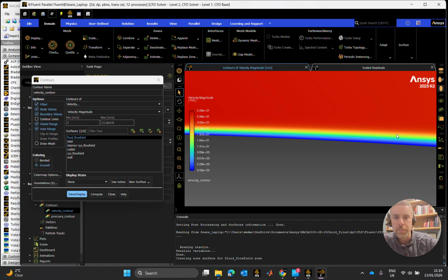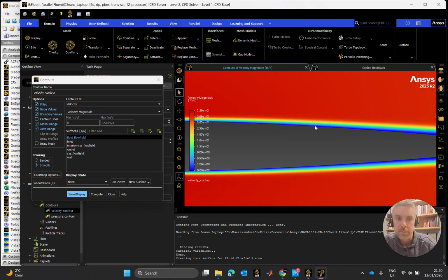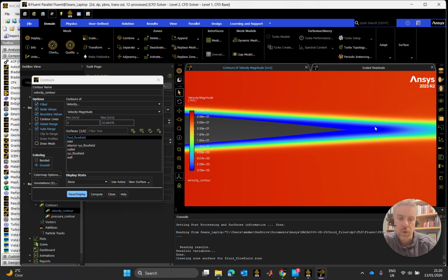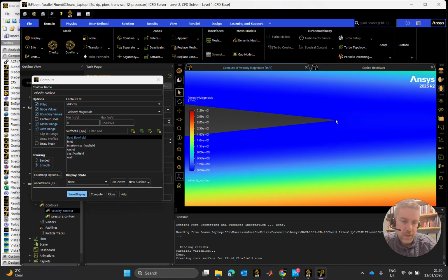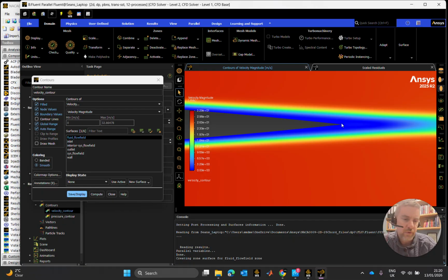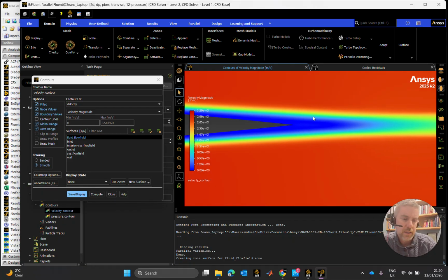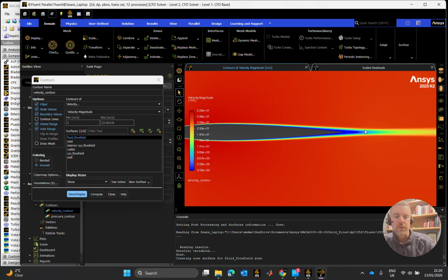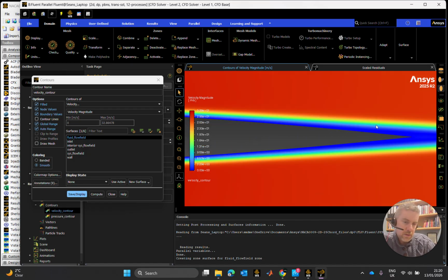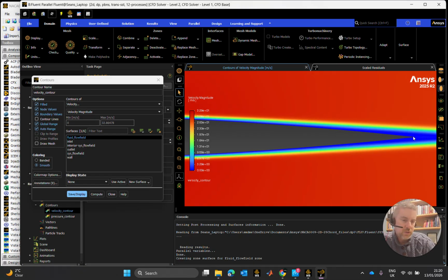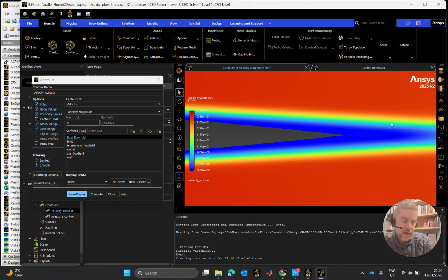It's just like adding a bump onto the airfoil, putting another part of the airfoil into the flow, which causes more drag. So yeah, what I will say is we have a very pointy edge here as well, which wouldn't be indicative of a true airfoil. If we had a more rounded edge, we mightn't get such a long stream out of that. But it's something there to look at. Your boundary layer there, you can see, is starting to come away from it here. Obviously, there's nothing more to stick to. And the two flows are convergent, which corresponds to that little section of higher pressure, that squeezing we've seen in the pressure contour.